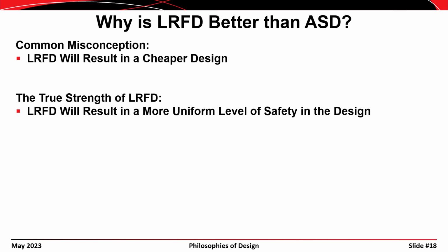If you tell somebody that you're using a factor of safety of 5/3 or 2.0, you really don't have any idea what the probability of failure associated with those factors of safety is. On the other hand, if you tell somebody you're using load factors and resistance factors that are based on a reliability index of 4.5, you can trace back, at least loosely, to the probability of failure associated with that. So that's why LRFD is superior in most people's opinions to allowable stress design.